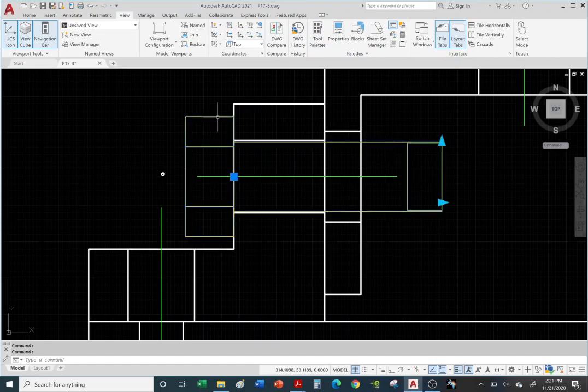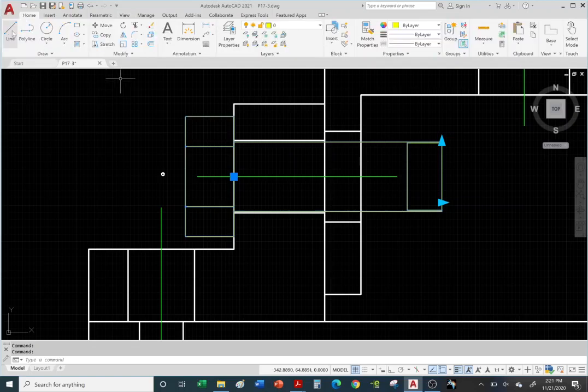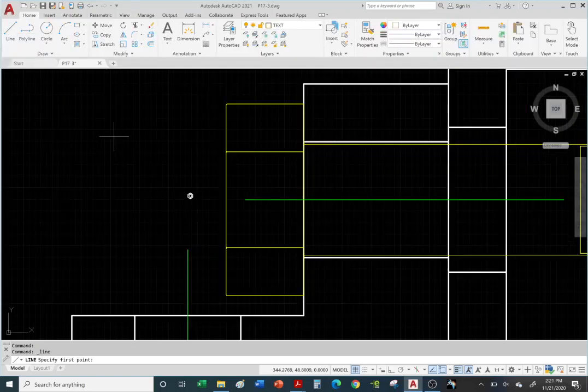Now this is a joined entity made up of a bunch of lines. And again, this is referred to as a block. I'll show you how to create a block in the next lecture. Okay, so I cannot alter this, but you know what I'm going to do is trace around it. I'm going to create lines. So let's go to the Home tab. I'm going to use the line command to create a side view of a hex nut.